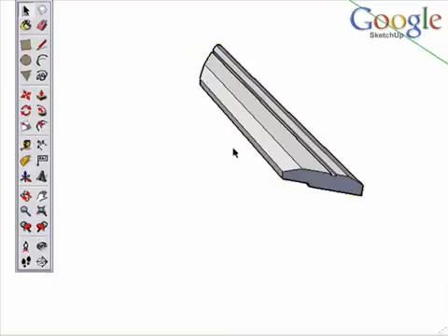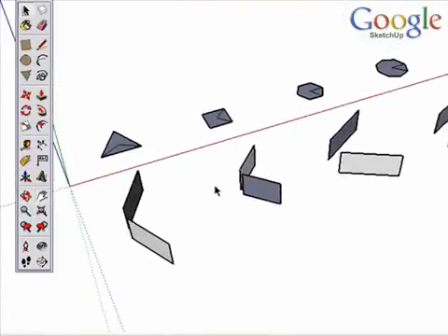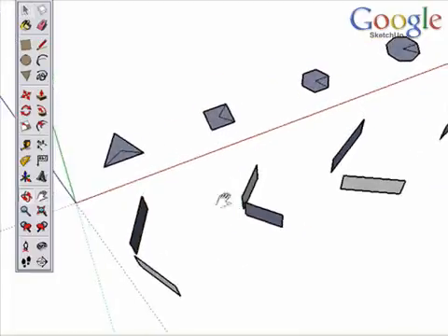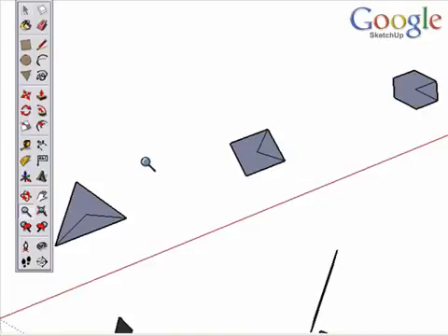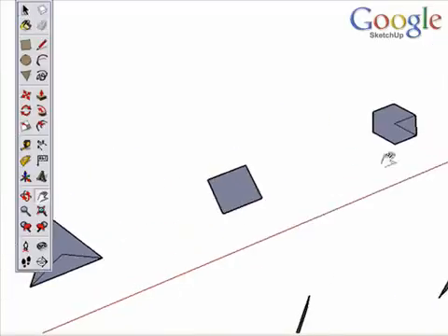Let's take some time to understand how you might go about creating some of these various jigs. So I've got a couple I've created here, and we're going to recreate a few. With the polygon tool, you can create any number of sides. Just start drawing a polygon and type 6S or 3S for different sides. And with the rectangle tool, you can draw a perfect square just by watching and being careful about drawing that. So here I've drawn a perfect square and a 6-sided polygon.